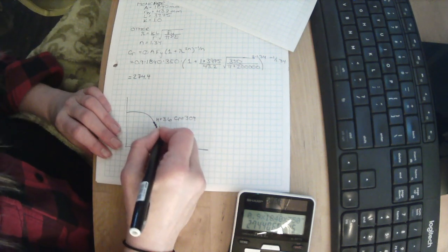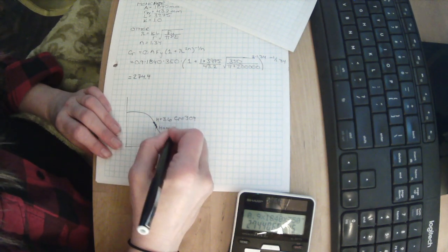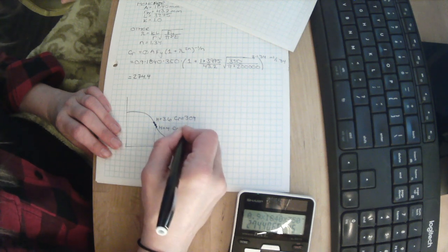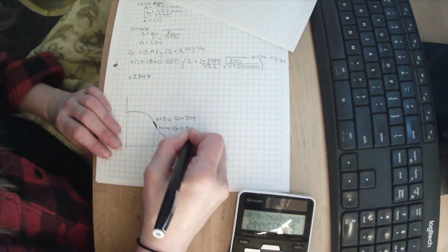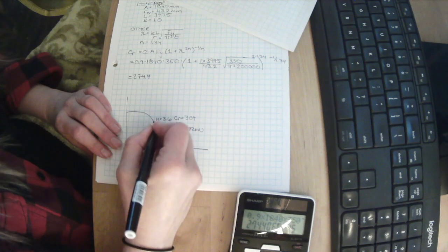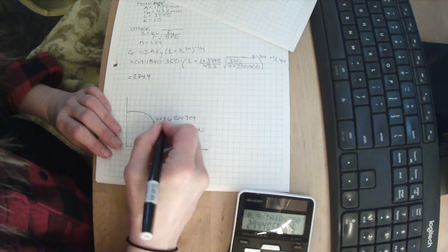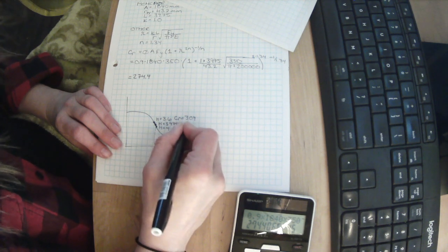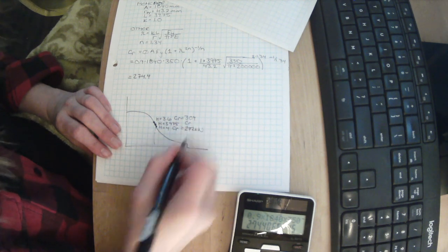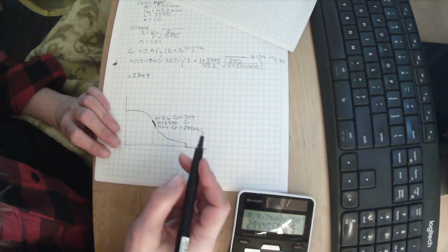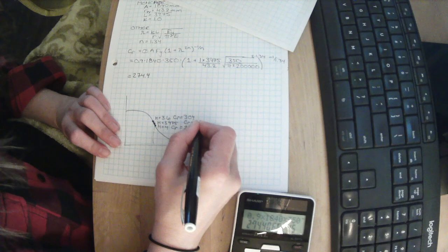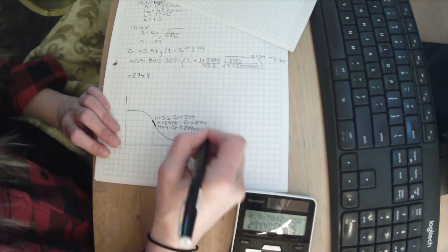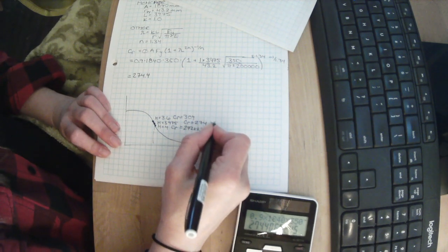Here, when the height was 4 meters, CR was calculated to be 272 kilonewtons. Here, for an H of 3.975 meters, we linearly interpolated it to be 274.3, and we calculated it to be 274.4, which in the chart, if they actually plotted it, they would say 274.